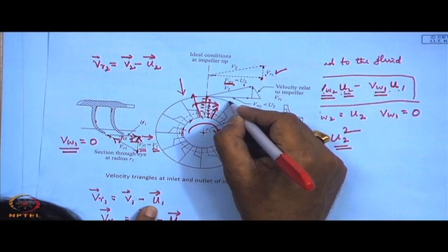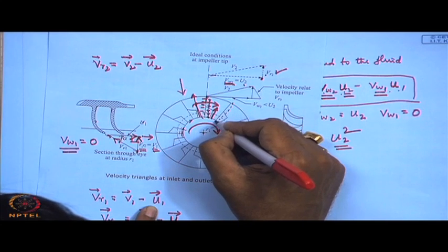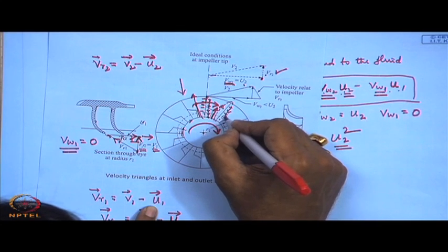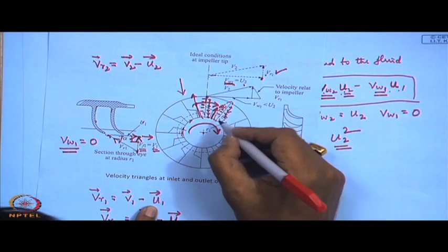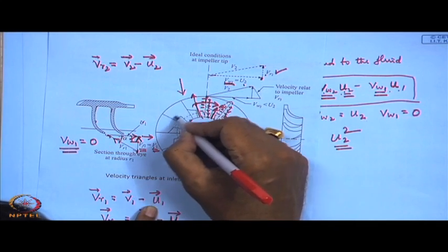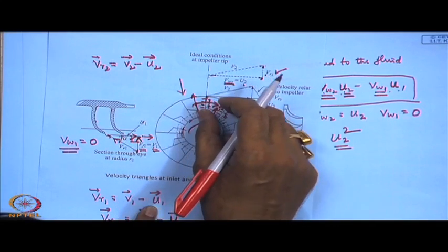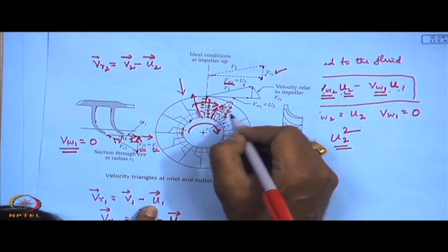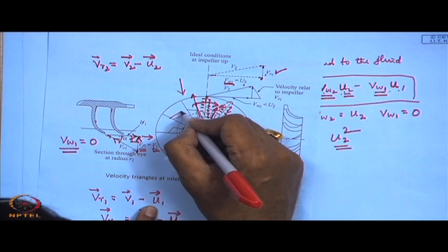So what happens here? I show you, it gives rise to a recirculatory flow in this direction. This is the higher pressure region, this is the lower pressure region. And this recirculatory flow, if you see this passage, this happens the same way in all passages, makes a non-uniform distribution of velocity, and that non-uniform is a skewed one.